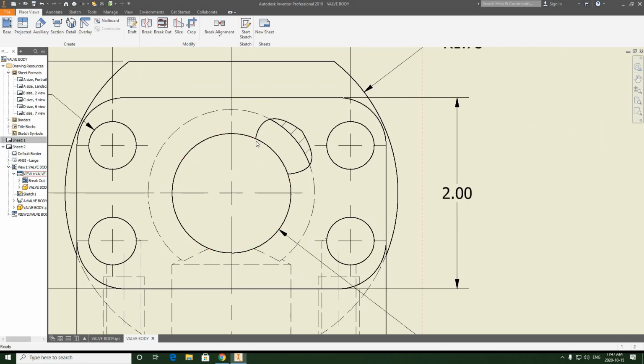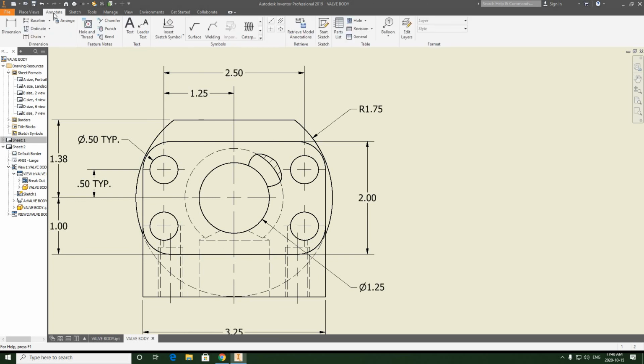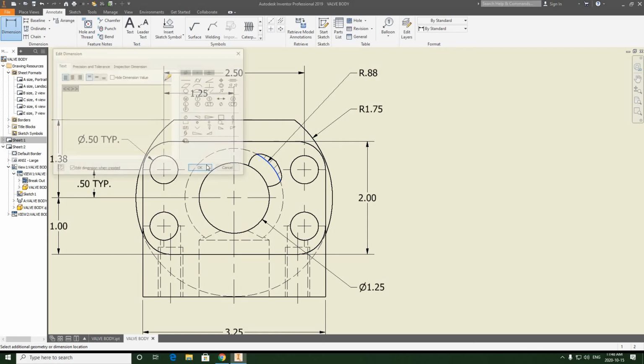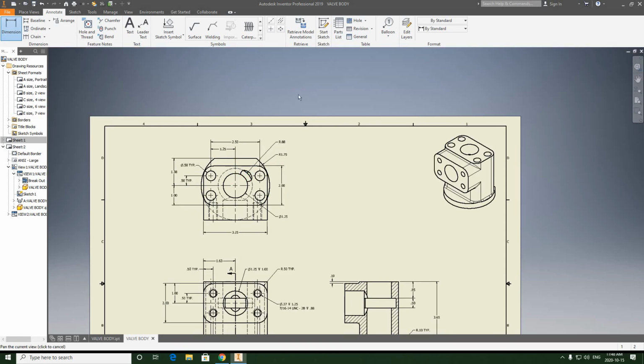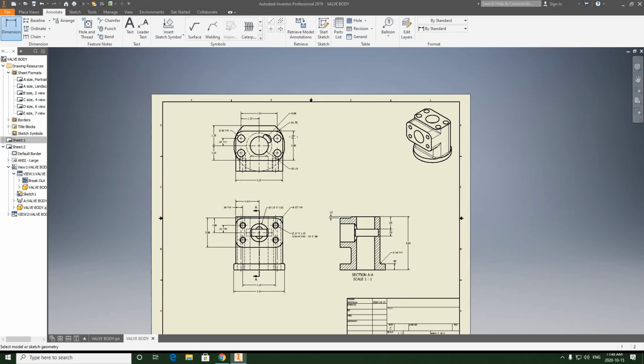It's not going to include the spline where there's empty space, but it basically just creates a section here and allows that part of the hidden line to become object line. So now I can actually run the dimension. This is allowed now. I'm not dimensioning to a hidden feature. And I'm going to have to cross over, unfortunately, an extension line here. It's just unavoidable. There's just too much going on. But that is how you dimension this. So that's something new, creating the breakout section with the point.